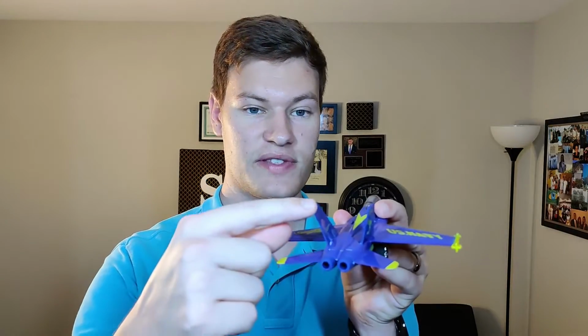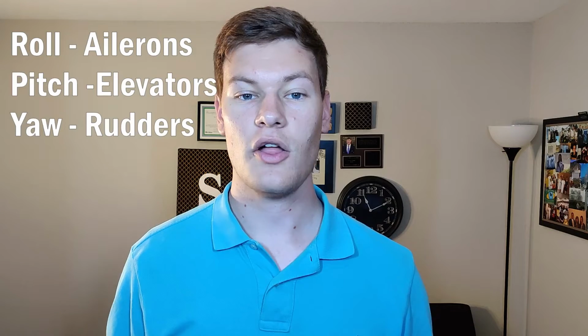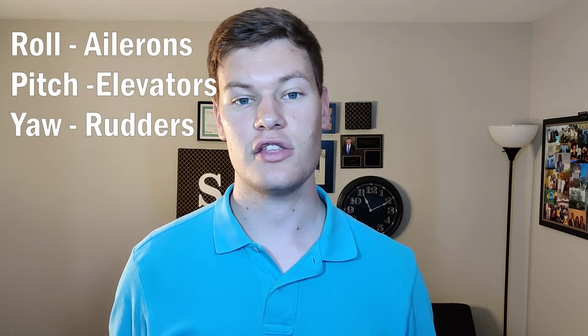The ailerons always work opposite each other. Right aileron goes up, left aileron goes down, and vice versa. The final primary control surface is known as the rudder. This is found in the vertical stabilizer, or the vertical portion of the tail in the rear. When the rudder is deflected to the left, this will push on the aircraft on the tail in this direction and will make the aircraft turn left. All 3 of these primary control surfaces control the roll, pitch, and yaw of the aircraft.